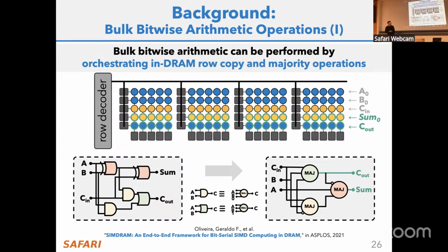So in the end, we are going to have 1 row with carry out of 1 and 1 row with the sum of the operation as 0. And the way that you read this is in a vertical way. There are some issues related to the bit shifting operation. So we are storing the data vertically inside the DRAM columns. And if you read that data in a vertical way, so here we have 1 and 0, which is 2, which is the result of the addition operation of 1 and 1. 1 plus 1 is 2 in Boolean logic.